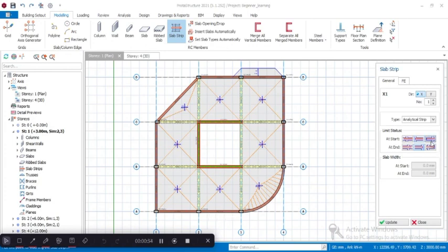For this cantilever now, this slab strip starts or ends beyond the cantilever slab. If you guys understand, either it starts or ends beyond the cantilever slab. So let me say it starts now. I'm starting at this point, or it ends at the cantilever slab. If that is understood, so now we'll start our slab strips.